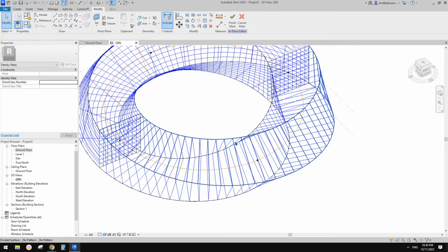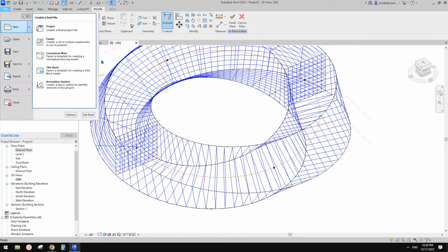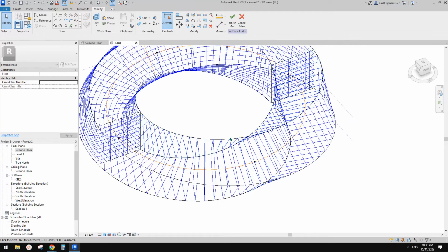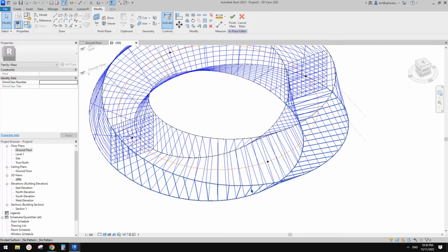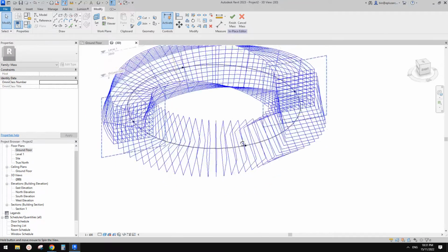So now we're going to place some framing. To do this, if you want to create a frame, it will be placed onto multiple divided surface. So you can't use pattern-based family, because pattern-based family can only be placed onto one surface. So you can place something like this.